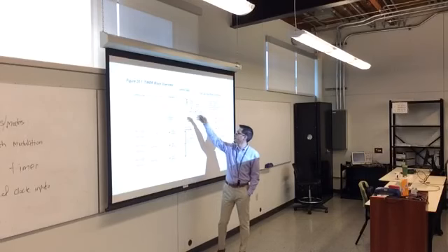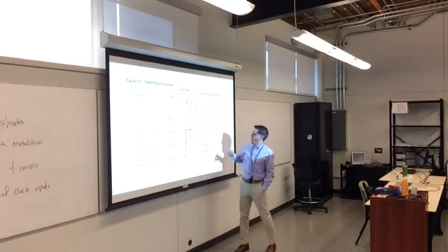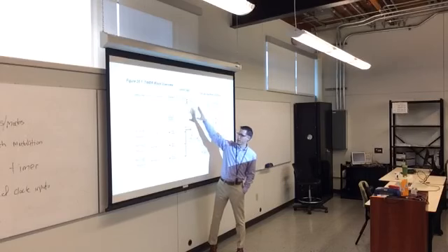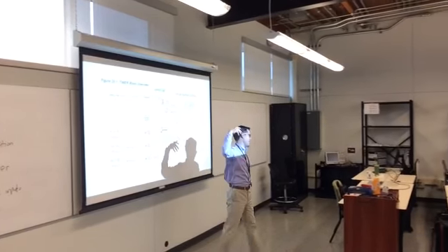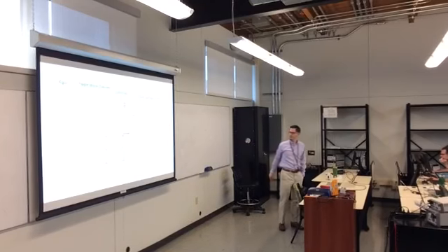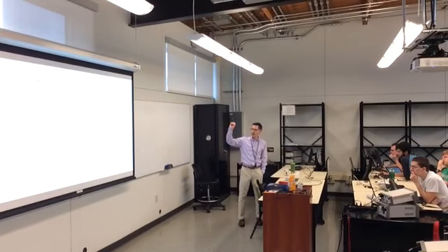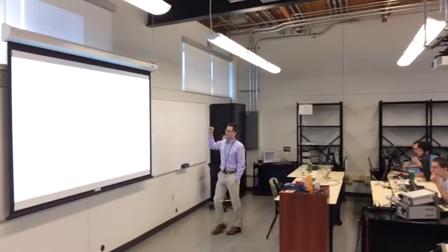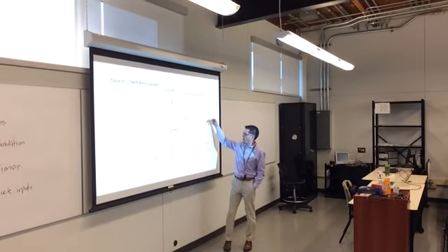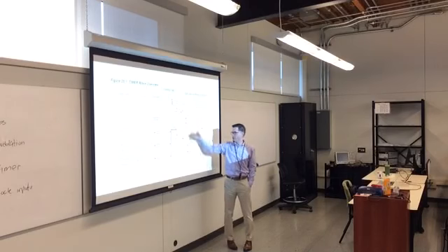And the main things you really need to concern yourself with are these registers up here that do the command and control of the timer. So the important ones are count, top, and counter control. And sometimes you can compare to some value for overflow. You can compare to 0 for underflow. You can compare to arbitrary values.